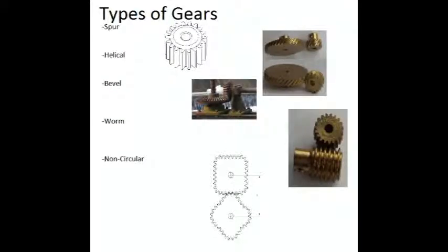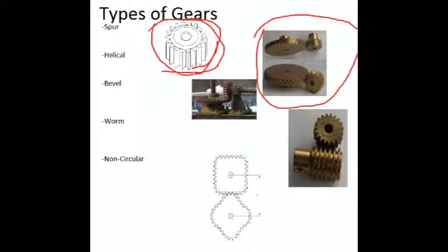There are many differing types of gears used in today's society for many different purposes. The spur gear is the simplest type of gear, shown here. They consist of a circular disc with teeth of the gear parallel to the center of the disc. Gear trains, that is, multiple connecting spur gears, can only be formed with parallel shafts in the case of this gear type. Helical gears, on the other hand, which are the most common gear, do not have teeth set parallel to the center axis and can therefore run in cross or parallel shaft configurations.